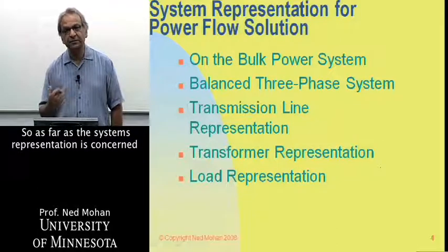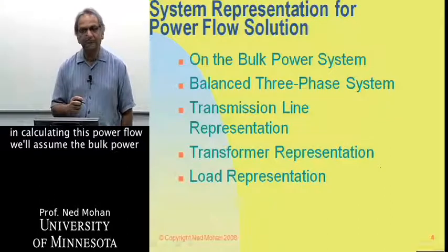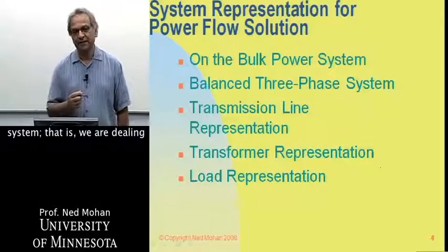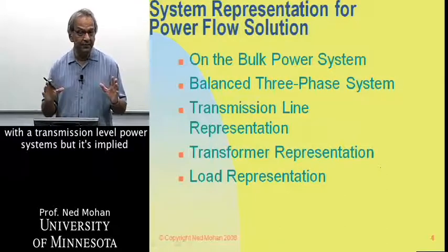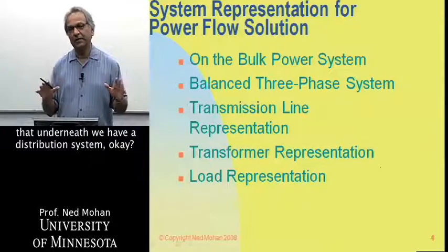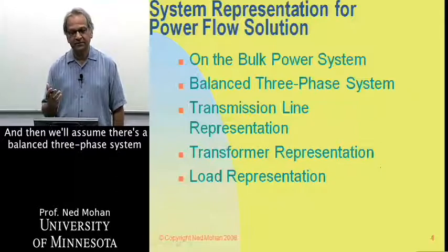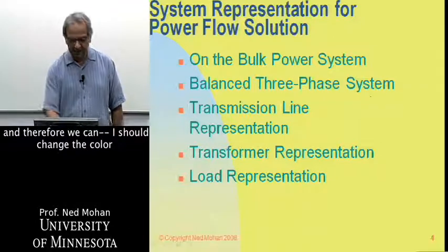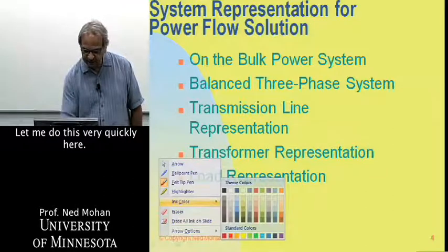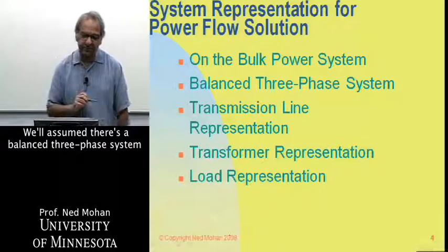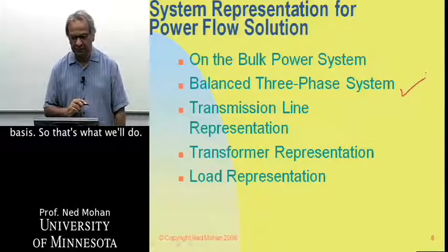As far as the system representation is concerned in calculating this power flow, we'll assume the bulk power system. That is, we are dealing with a transmission level power system, but it's implied that underneath we have a distribution system. Okay, and then we'll assume that it's a balanced three-phase system, so we can model it on a per-phase basis. So that's what we'll do.